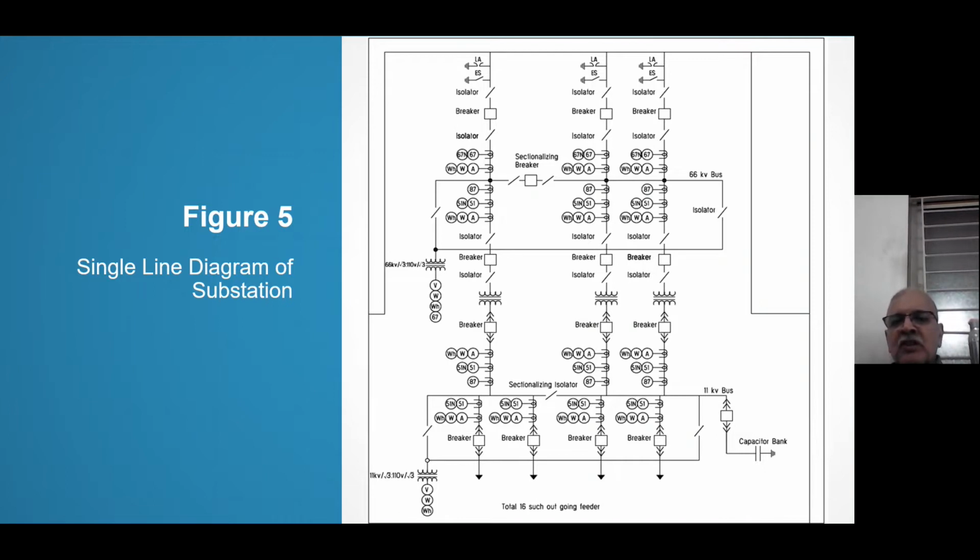So this is what I know from this. Then I'm coming to the bus. This is the sectionalizing breaker, and this is from the other half to the PT. The PT is only one. It is feeding voltmeter, wattmeter, potential coil, whatever meter, and 67 because the directional relay needs voltage also. So I'm feeding 67 also from the PT.